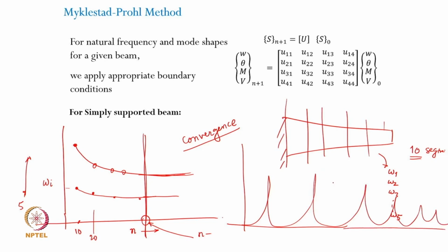But if you are not going to operate at this speed of operation, if your operating speed range is limited within a couple of natural frequencies, there is no point in evaluating accurately the 10th mode and the 15th mode and 20th mode, right? So in general, it suffices to ensure that the first 5 natural frequencies are accurate enough. That number is also not sacrosanct, just approximate.